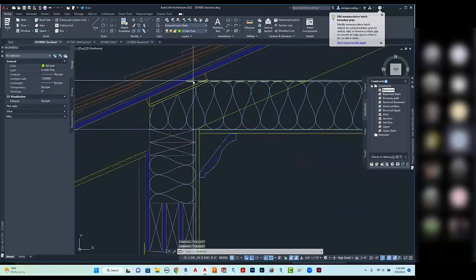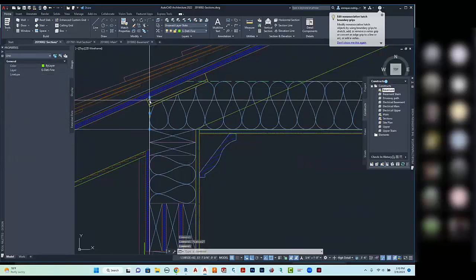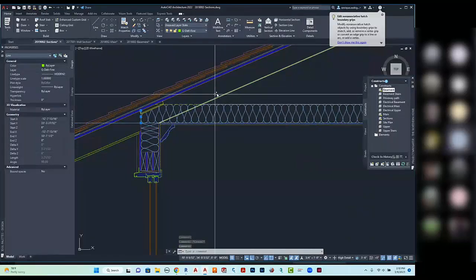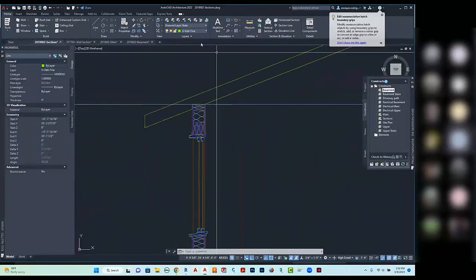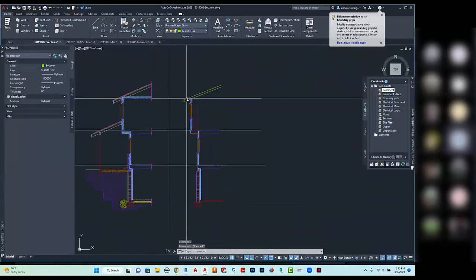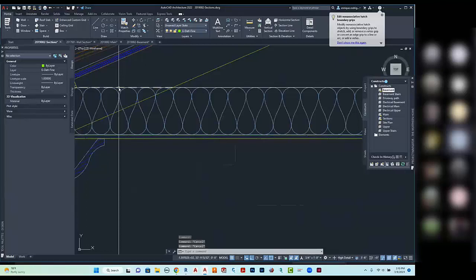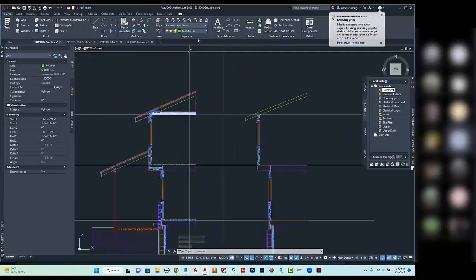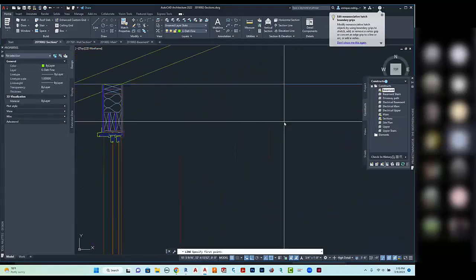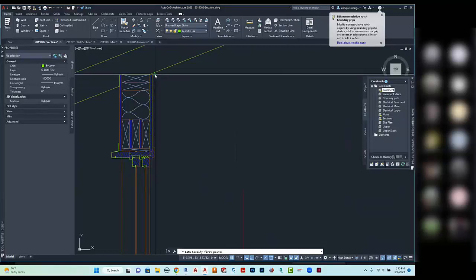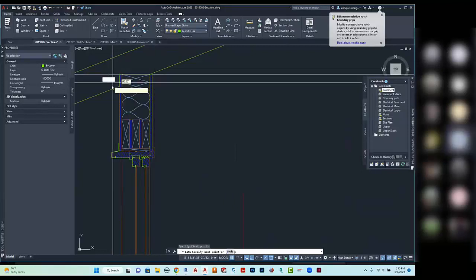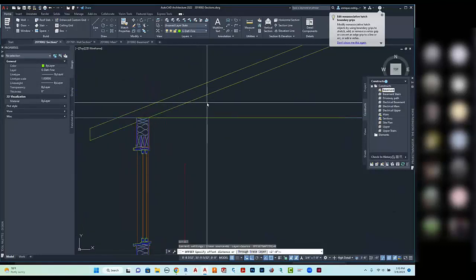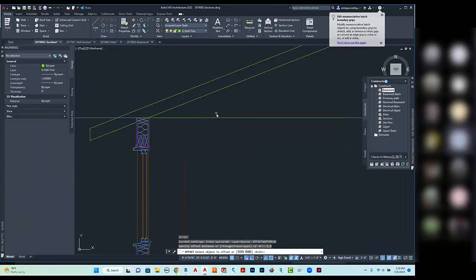So if you notice, there's some hidden lines here and here. And what those represent is the ceiling joist hiding behind the rafter that we're doing at an angle. So let's see what they used for that. Still G detail fine, but they did an override on the line type. So let's go ahead and do a line right in here. I'm just going to draw a line from here to roughly here. I'm going to offset it 5.5, which is the actual dimension.